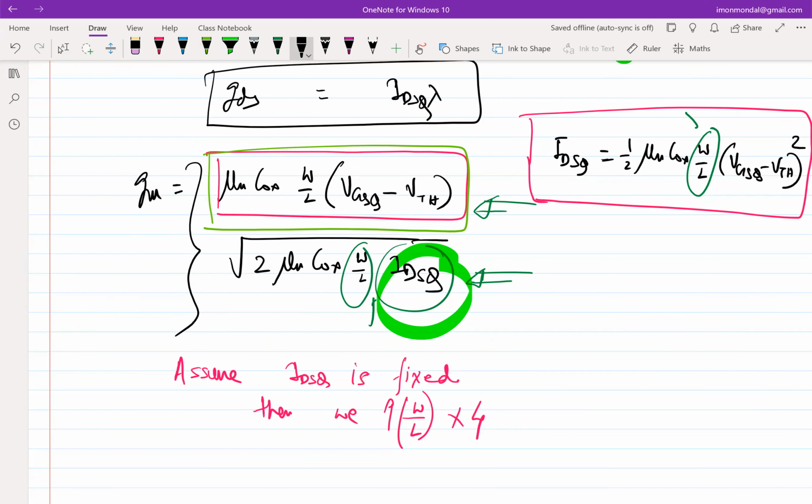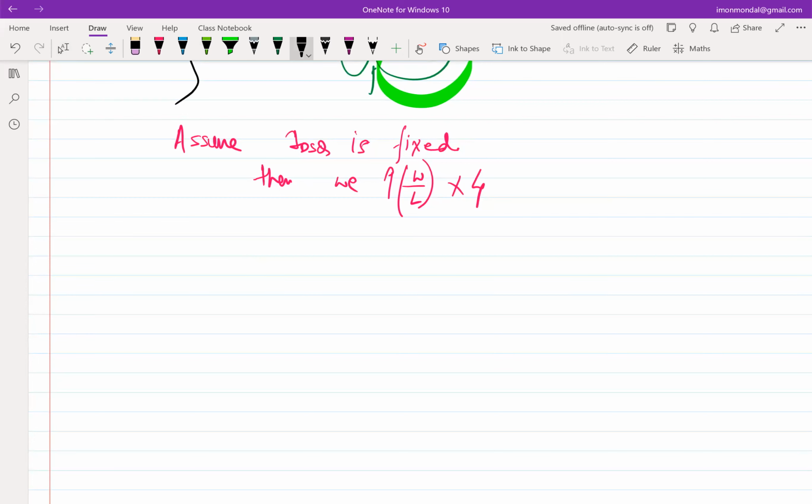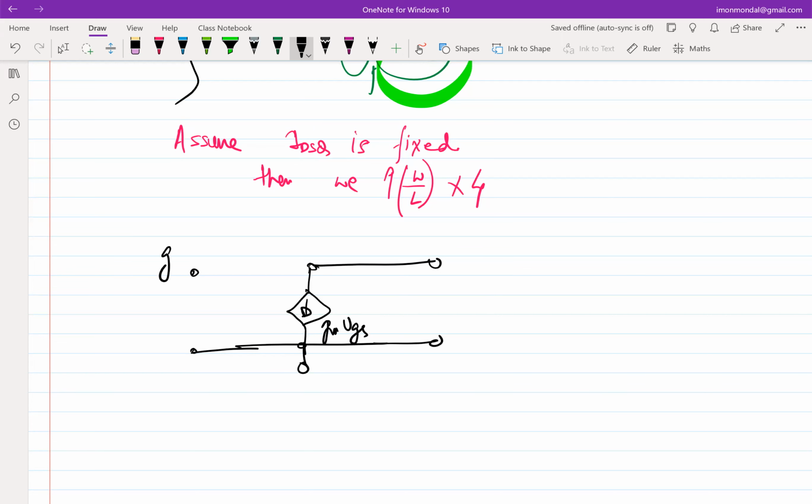Okay, fine. So now what is the model of our MOSFET? What is the incremental model? The incremental model of our MOSFET changed from this, which was GM times VGS between source and drain, to having a VDS-dependent term as well.